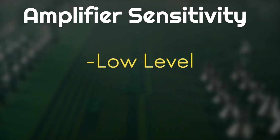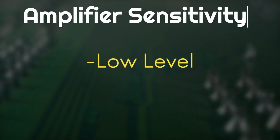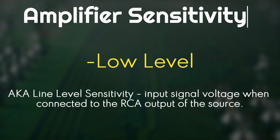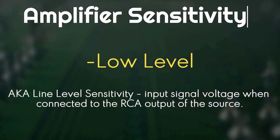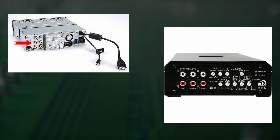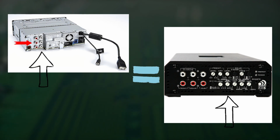Low-level sensitivity, also known as line-level sensitivity, is the input signal voltage that an amplifier needs when it is connected to the RCA outputs of the head unit or the source unit. The sensitivity rating of an amplifier should match or be lower than the output signal voltage of the head unit or source unit that you are connecting to the amplifier.